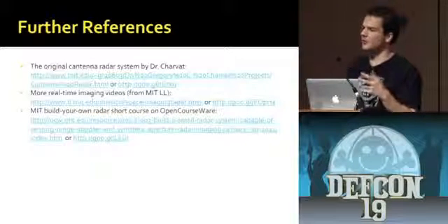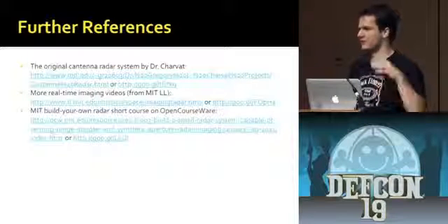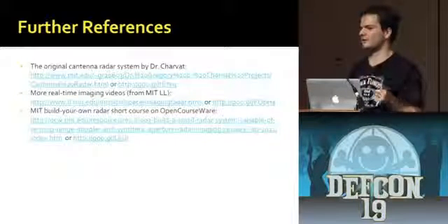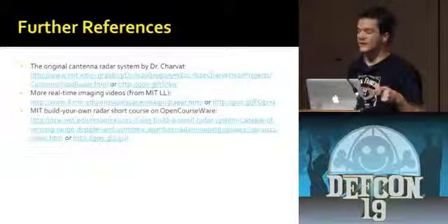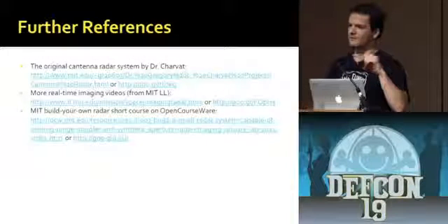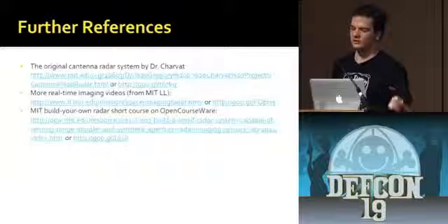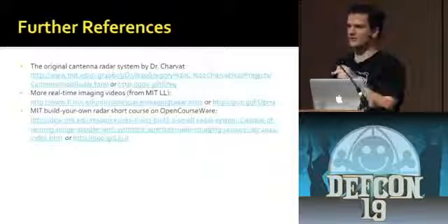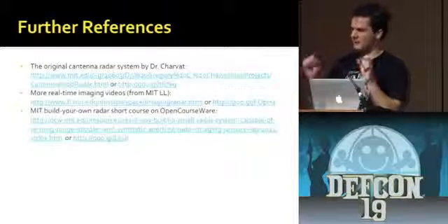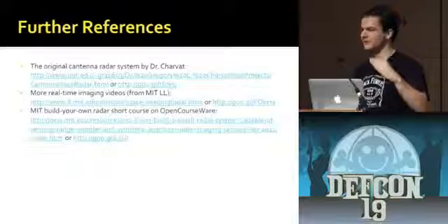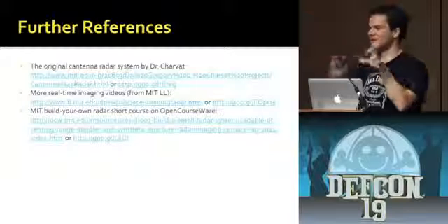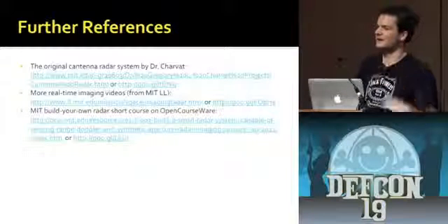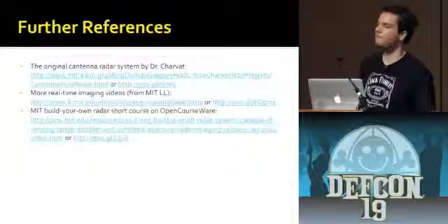So it wouldn't affect it too much, but that all depends on your chirp rate and your bandwidth and a bunch of other factors. So yeah, you could make it have an impact or not. And the other thing is there's actually a way of disambiguating those, because I didn't talk about this, but you can chirp up and you can chirp back down. And if you think about it, the effects are a little bit different, because the Doppler shift is always going to change the frequency in one direction. But if you chirp the other direction, it'll shift it backwards. So all you have to do is figure out what's happening there, and you can disambiguate them.